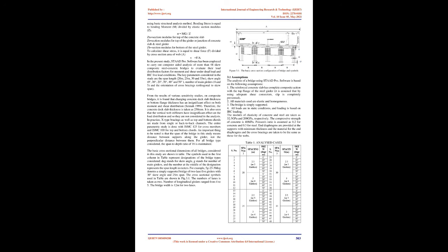16. Peter Kocsis, P.E., M.ASCE, 2004. This paper evaluates the American Association of State Highway and Transportation Officials, AASHTO, line load and live load distribution factors. The standard AASHTO formulas for live load in some cases underestimate the live load moments by as much as 40%. This paper shows how more reliable distribution factors can be obtained for line loads, AASHTO truck loads, and non-AASHTO live loads. A user-friendly computer program for calculating distribution factors is discussed.